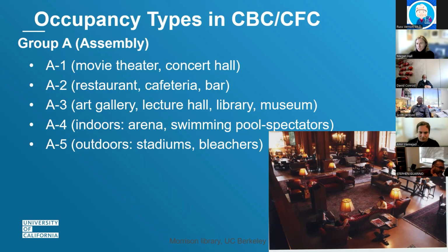However, certain occupancies do have material-specific restrictions that are more strict than the MAQs. For example, toxic gases. You can't store toxic gases in a movie theater.